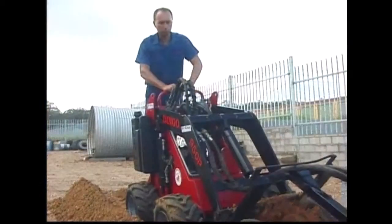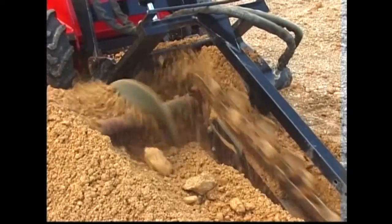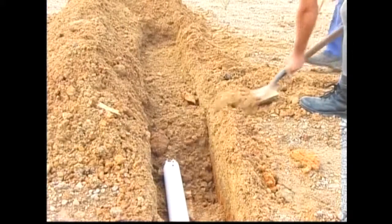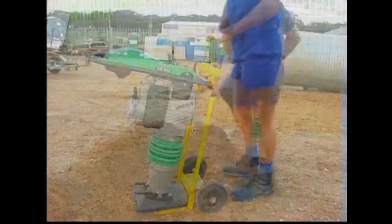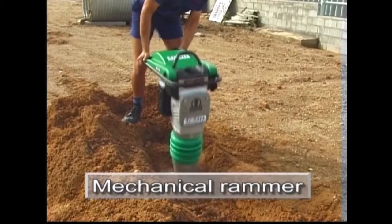Mechanical trenching machines produce neat trenches with minimal disruption to surroundings. Once the pipes are laid and the trench backfilled, it may be necessary to compact material to minimise future subsidence. This can be done using a mechanical rammer.